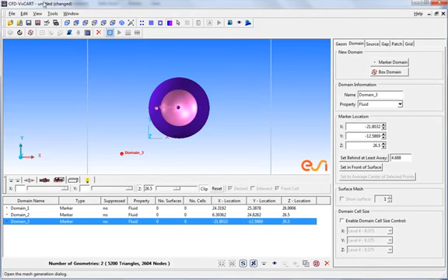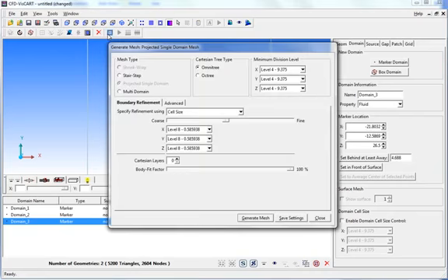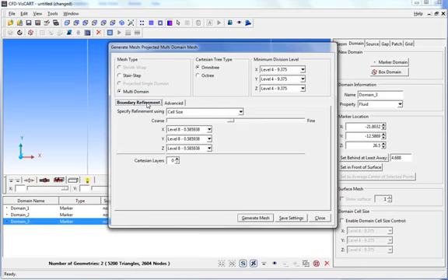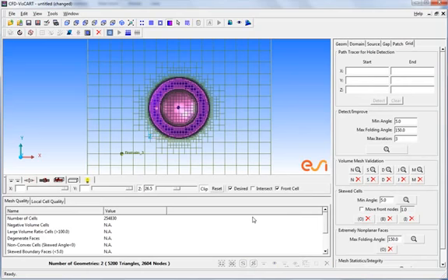Let us click the Generate Mesh icon in the toolbar. As the model now includes 3 domain markers, the projected single domain meshing option is no longer available. We will select the multi-domain meshing option. With this meshing option too, several advanced options are available. We will retain the default settings for them. Let us generate the multi-domain mesh. Once the mesh has been generated, you will see the mesh in all the 3 regions, colored differently for easy visualization.